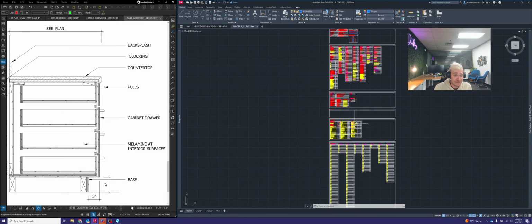Okay. Next up, we have our upper cab. And fortunately for us, we only have to draw one section for all 3 of these cabinets, because if you're cutting through any of these, it's going to look exactly the same from one to the next. So we'll take a look at our elevation view and then our section view here, and just make sure that we have this correct. So let's see, section view is view 6 on this page, which was this guy here.